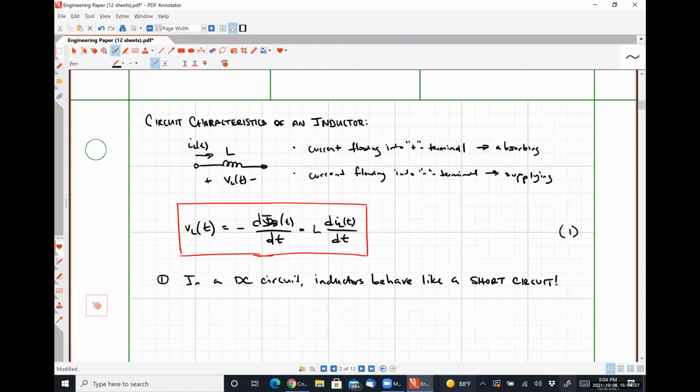So for any DC circuit that we are analyzing, or let me rephrase that very slightly. For any circuit at DC steady state, which will become very important in about 2 days, we can treat an inductor as if it were a short circuit and lose no information whatsoever. Okay, no voltage drop over it, which means it's not absorbing. Well, I don't want to get into that bag of cats, but no voltage drop over it. Treat it as a short circuit.